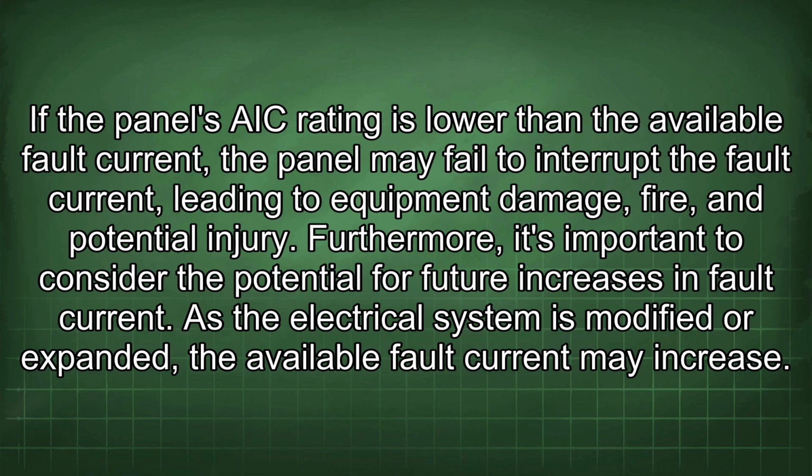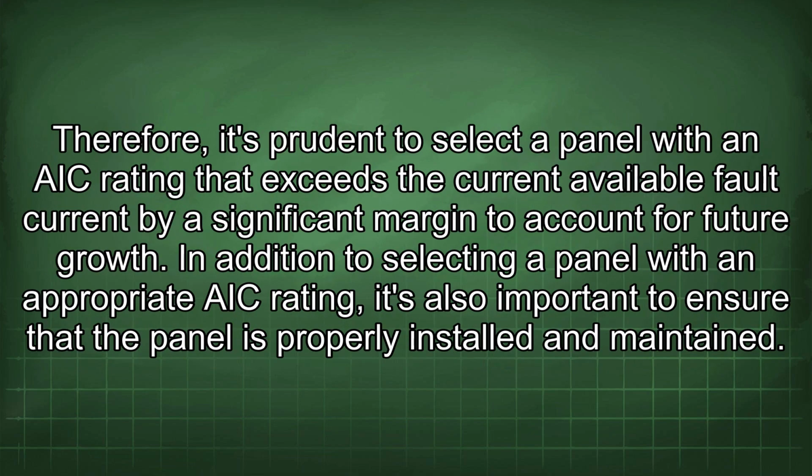Furthermore, it's important to consider the potential for future increases in fault current. As the electrical system is modified or expanded, the available fault current may increase. Therefore, it's prudent to select a panel with an AIC rating that exceeds the current available fault current by a significant margin to account for future growth.